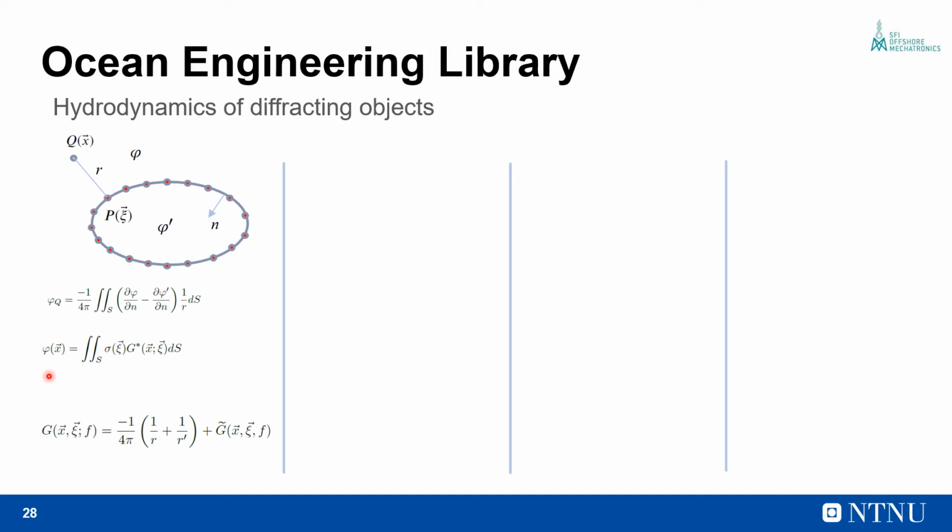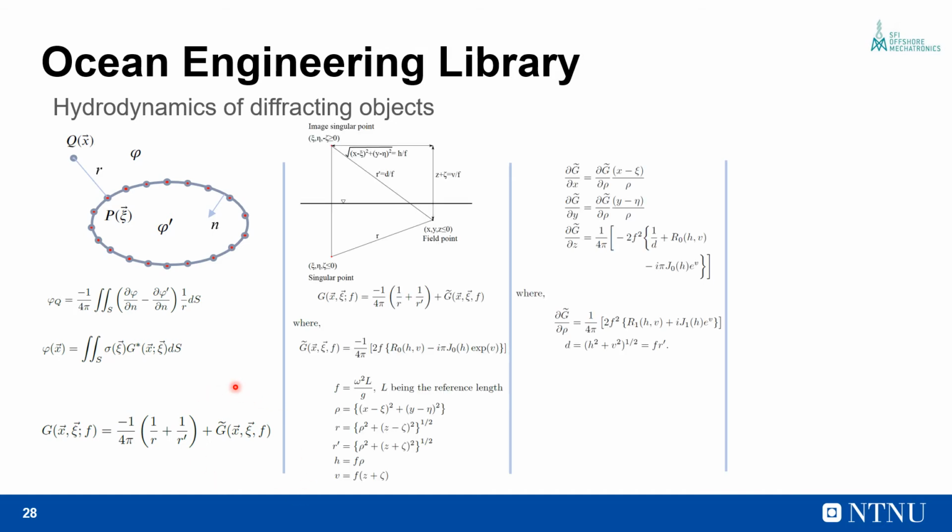In the case of a free surface and waves, the Green function changes. It now has a stationary part and an oscillatory part to account for the effect of waves. Telste and Noblesse give numerical expressions for the evaluation of the wavy part of the Green function and its derivatives. They also provide the printout of a Fortran code along with their publication. We replicate the Fortran code and wrap it for use in Python using the F2PY interface.